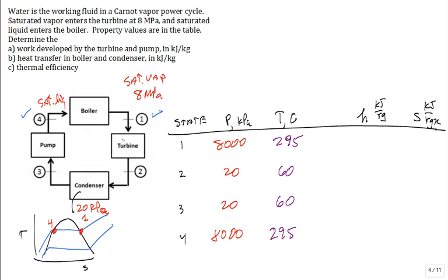You're going to do the best turbine, reversible. It's also well insulated. It's adiabatic, it's reversible, hence it's isentropic expansion. It's a straight line down as well as a straight line up through the pump. 1 to 2, straight line down. State 3 to 4, straight line up. All right? Then it goes across and across. That's your whole cycle on a TS diagram.